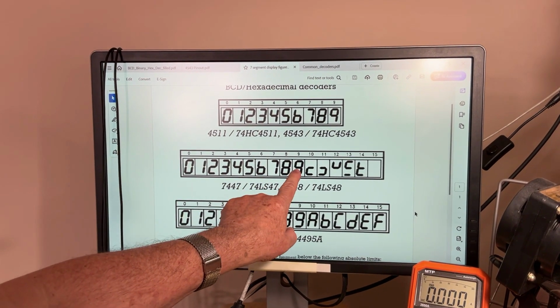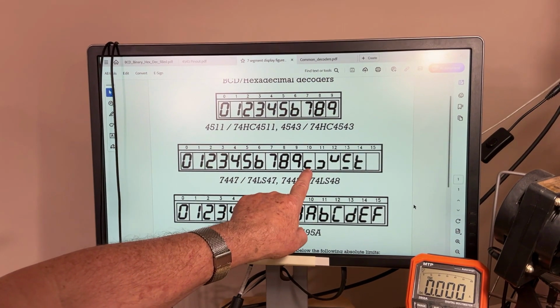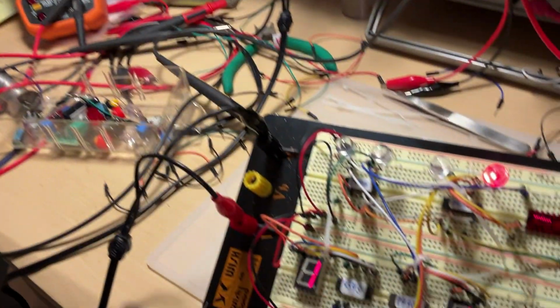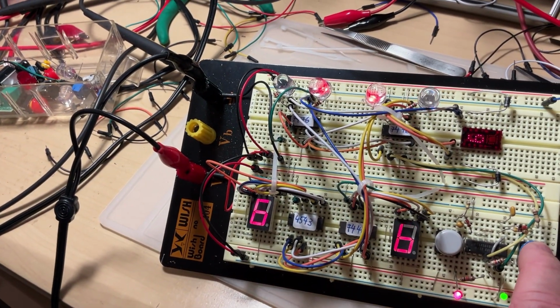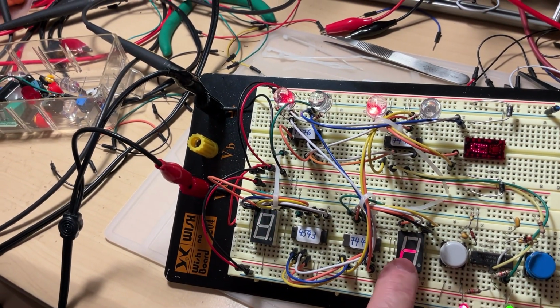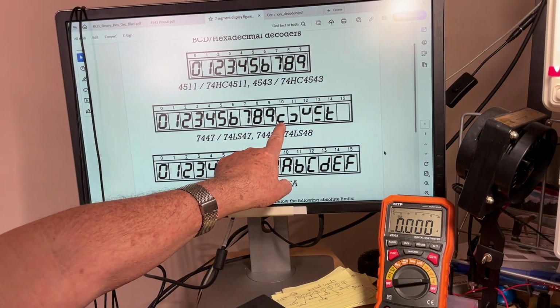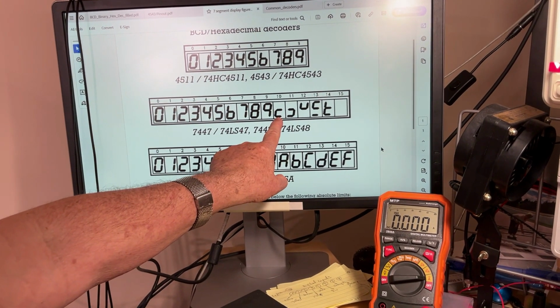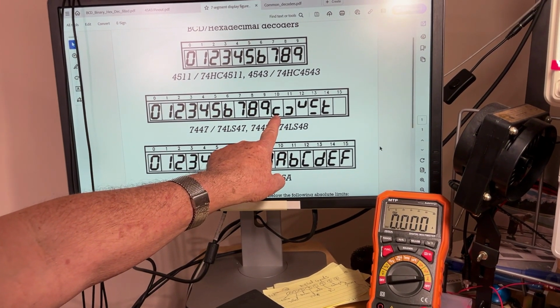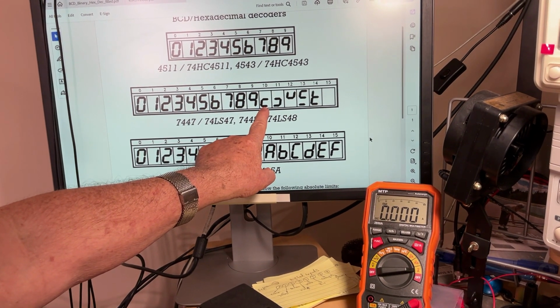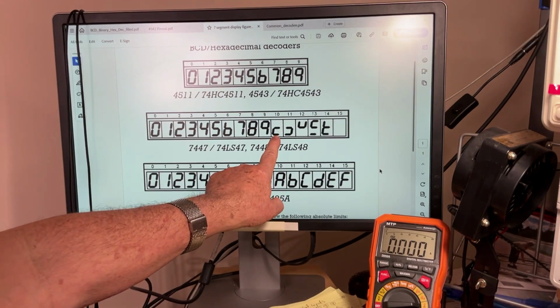9 is okay. But when you see that particular symbol, which is a kind of lowercase C, and I'm showing it here again, this is not C. This is actually representing the number 10. Because again, normally for the number 10, you need 2 digits. But if you see that on 1 digit, it is because of the decoder. It was made by the manufacturers to show you that.